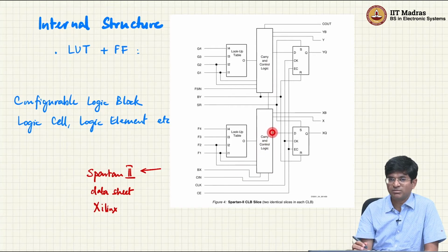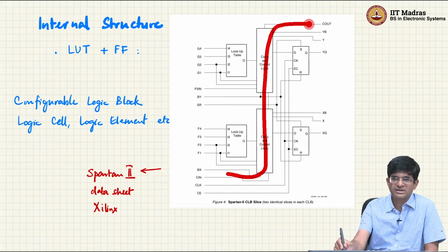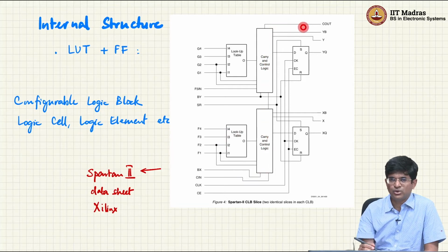Why was it put in there? Because of an observation from the people who built FPGAs that addition was one of the most common operations that the users of FPGAs were trying to do. You can of course build up half adders and full adders using these lookup tables, but it's much more efficient to use custom logic which is hand tuned or hard coded to do just that.